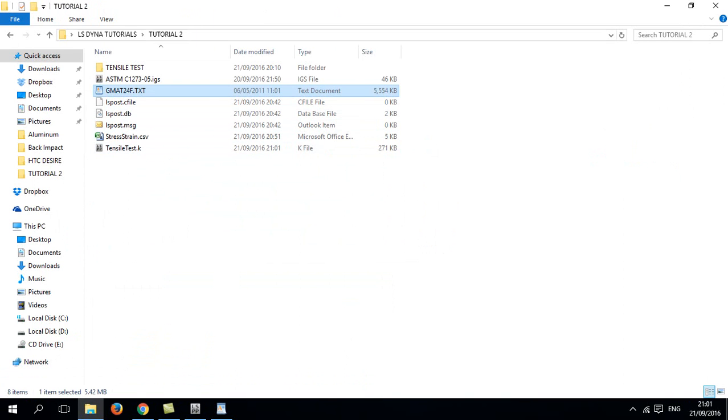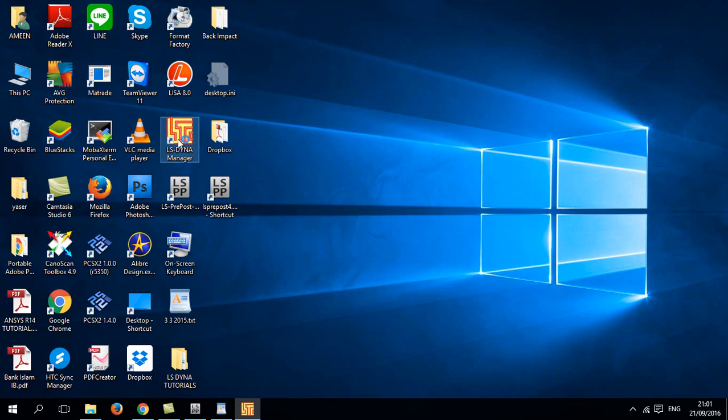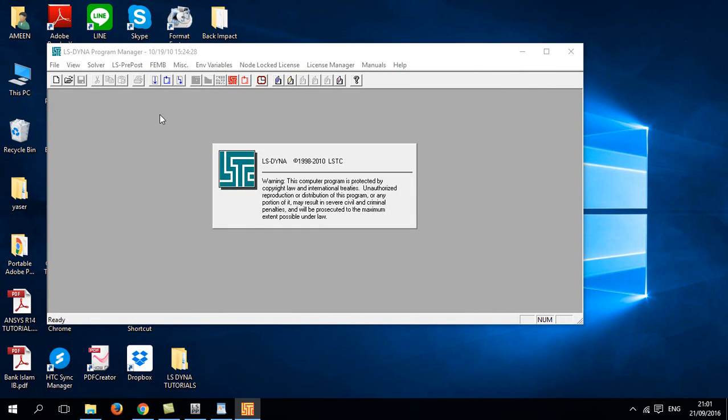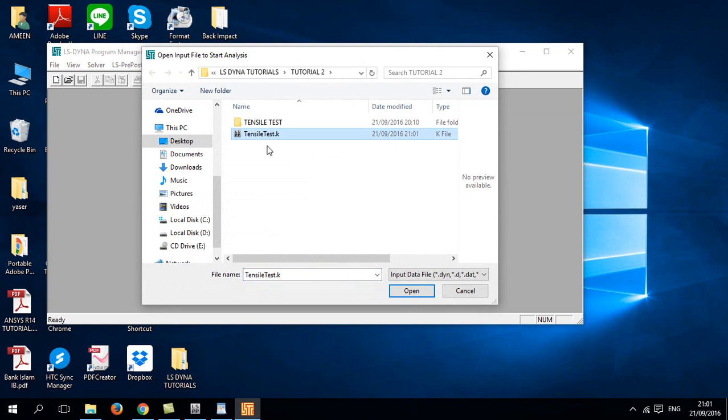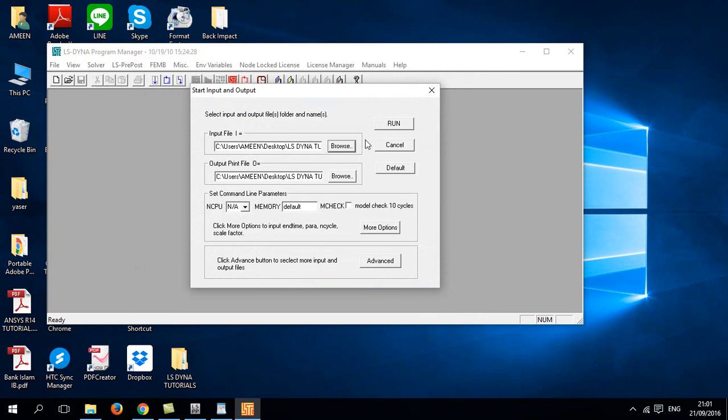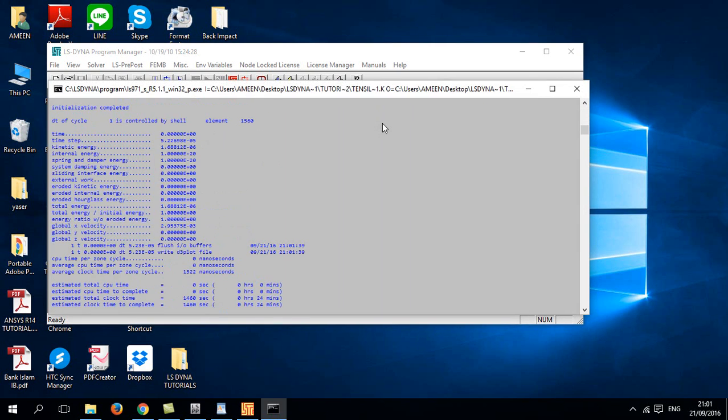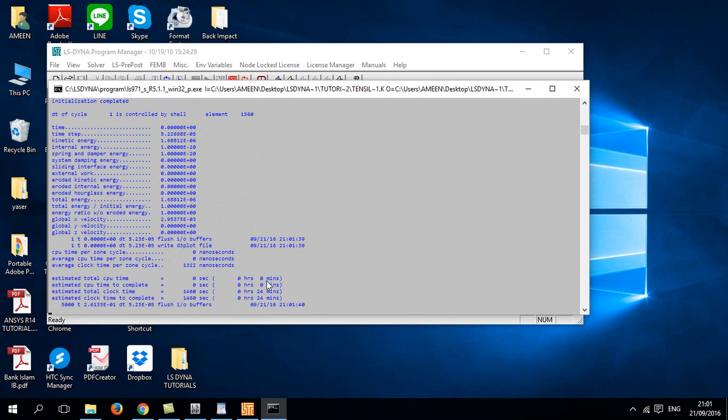So you go down here, you open the manager, the LS-Dyna manager, you run the simulation. This one, click this the file that we just did, open, and here I put 8. This one I put 3 and 0 0 0 0 0 0 0 0. This one depends on your PC. Okay, it says 24 minutes.